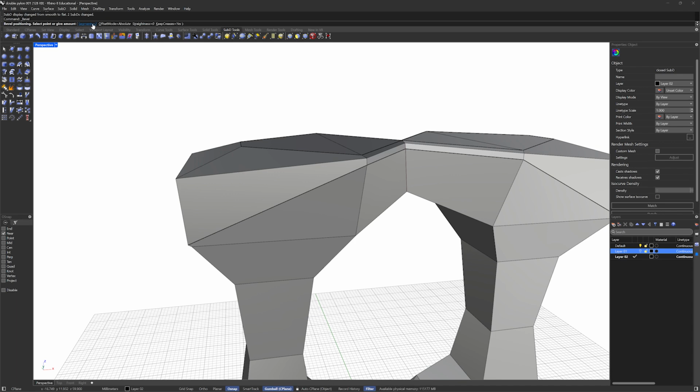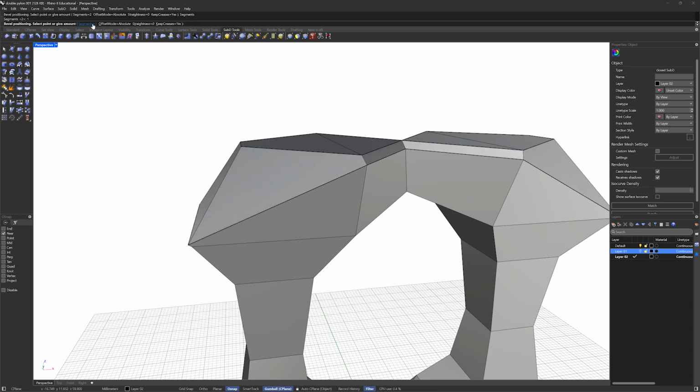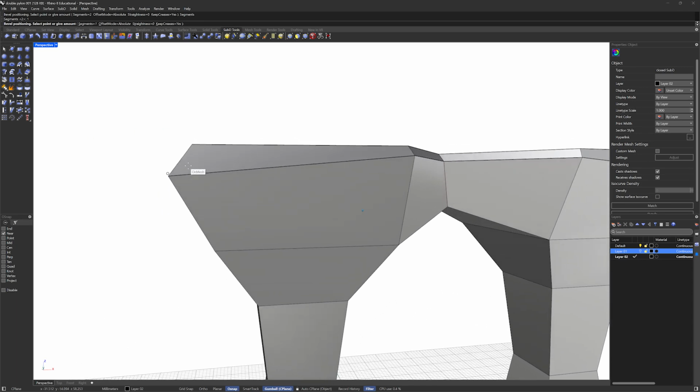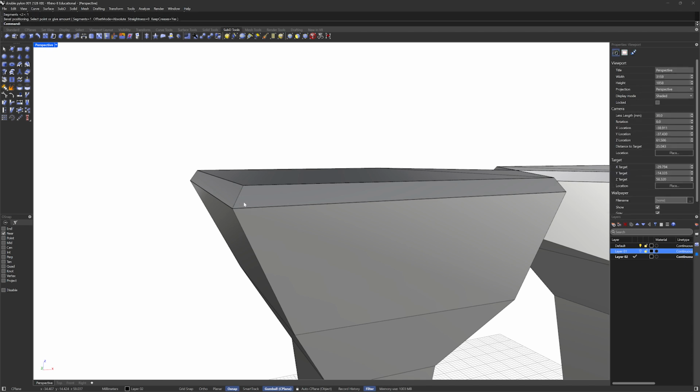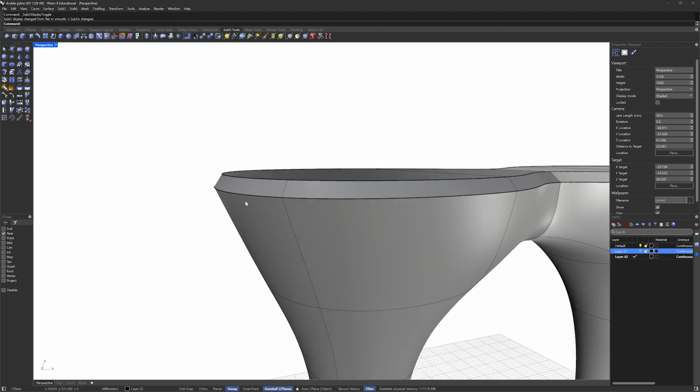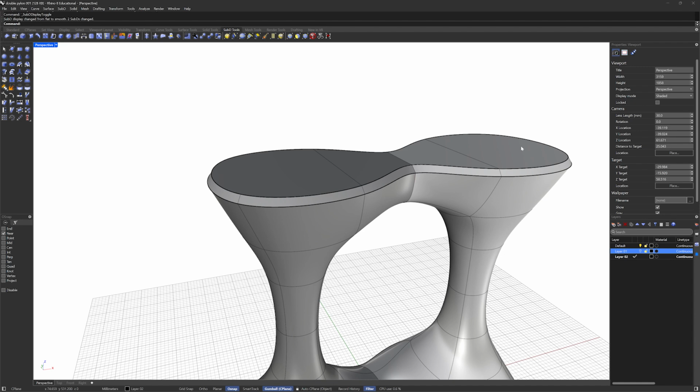I think I'm going to start off just by showing you a one segment bevel. And here's where we have to kind of get close to the corner. So all we're doing is adding one more face between that top flat surface and the sloping side. And it looks a little bit unimpressive right now, but when we hit the Tab key, we'll have a nice little fillet.